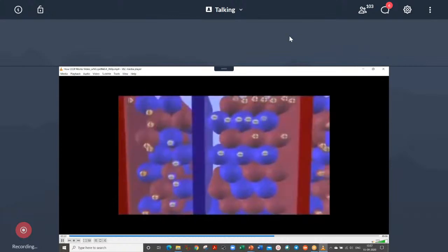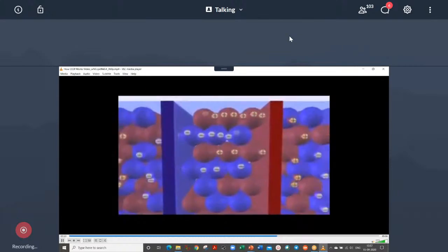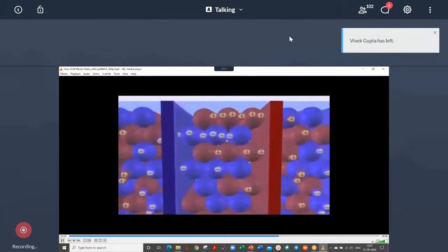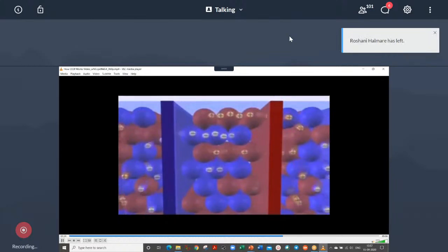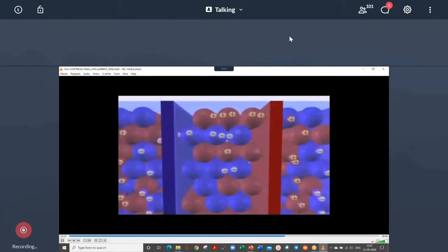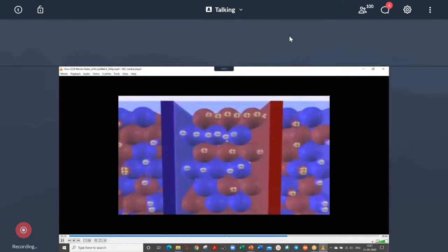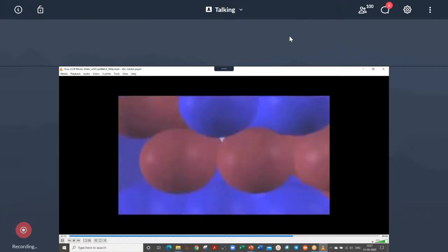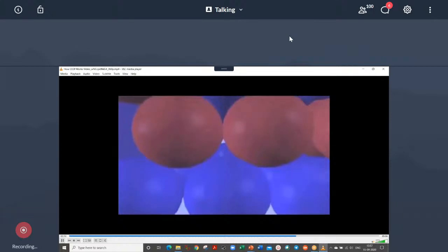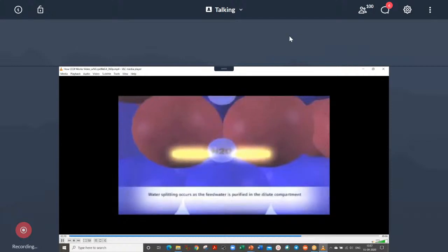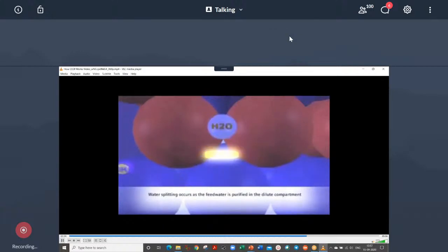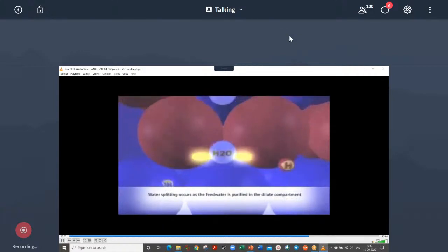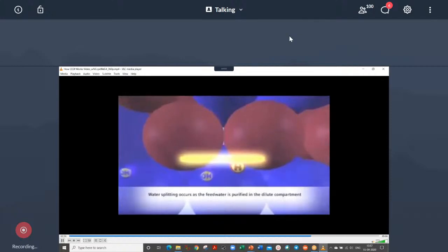At the top of the purification compartments, the ion concentration is at its highest. Here, the surface of the resin beads acts as a conductive path, effectively moving the ions to the membrane. At the lower end of the purification compartments, where the ion concentration has been reduced to the parts per trillion level, the electric field becomes concentrated between the resin beads and the surrounding water. When this localized voltage potential exceeds approximately 0.8 of a volt, an electrochemical reaction occurs, and water molecules are split into hydrogen and hydroxide ions, which are essentially acid and caustic.